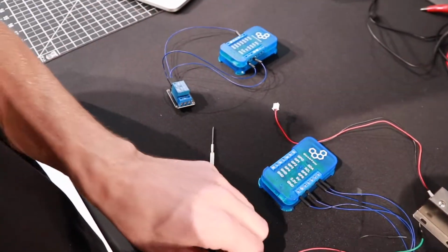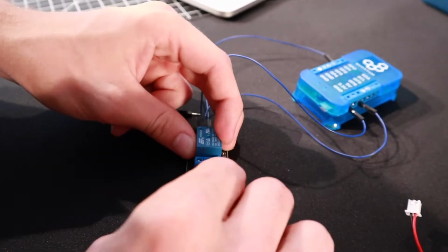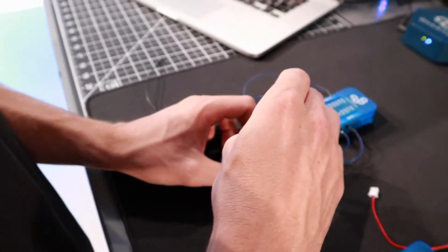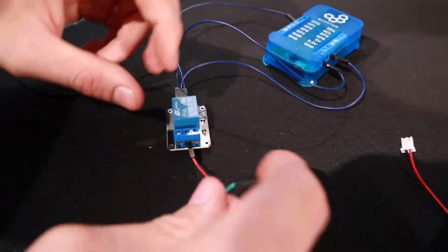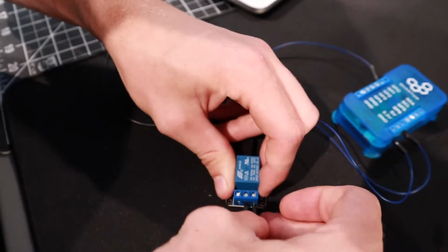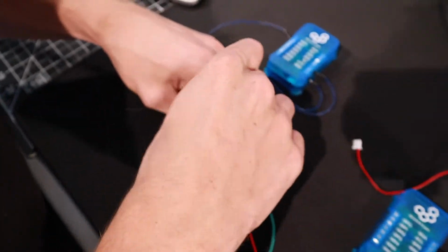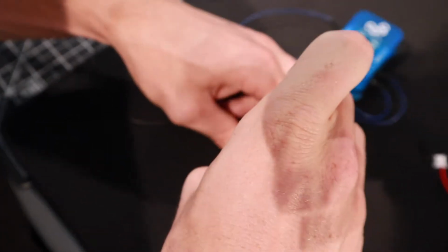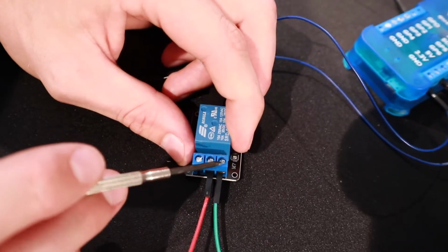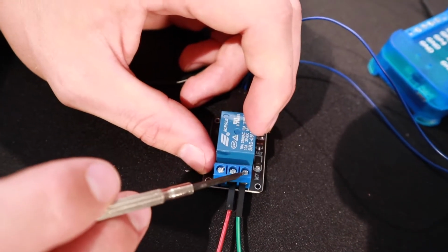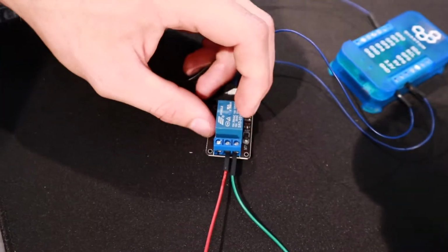Now we'll move on to the high voltage side of the relay. In this middle port, we're going to connect 1 male-male jumper wire. And then on the rightmost port, we're going to connect another male-male jumper wire. I saw there's open and close. There's normally closed and normally open, and that's either side. For this particular relay, the side that we're going to use in this circuit is the normally open, so that when we switch the relay on, it will then close the circuit,